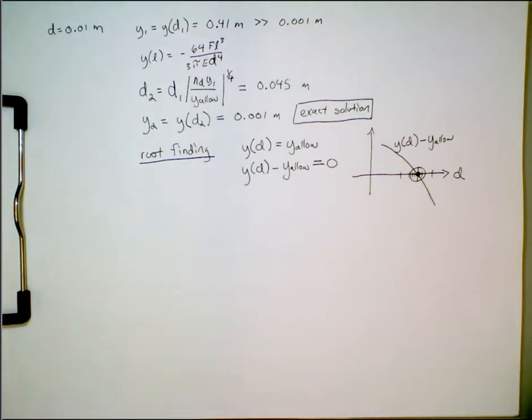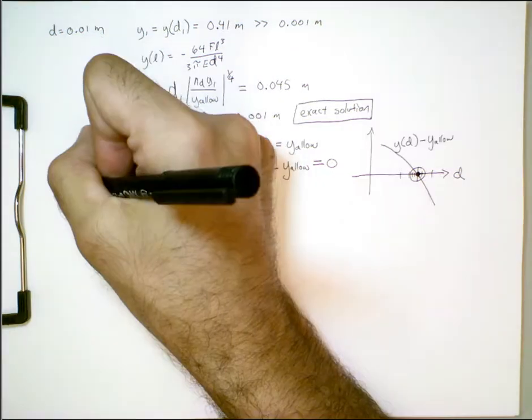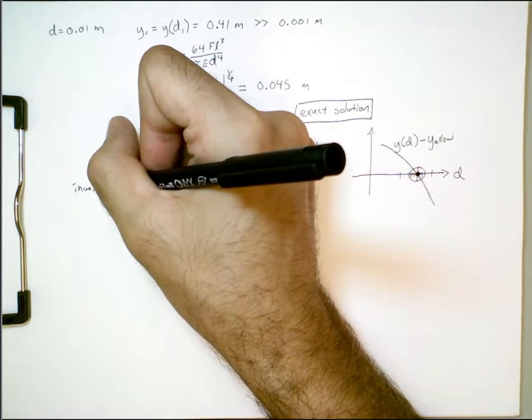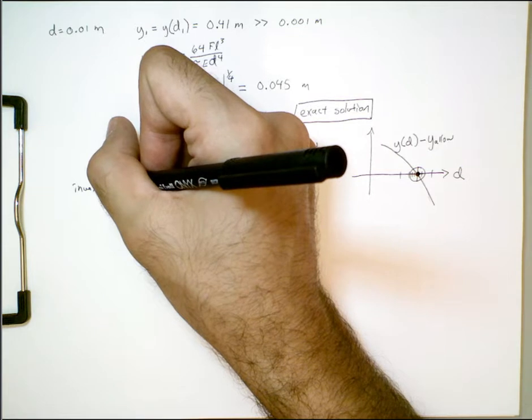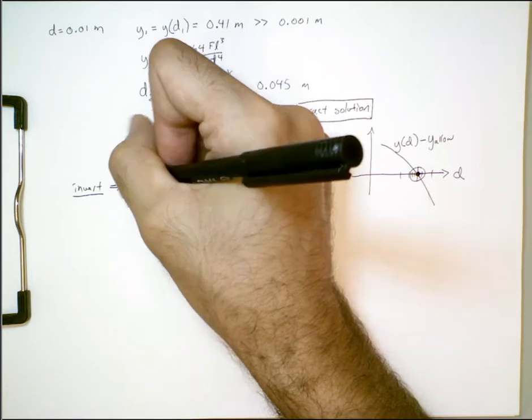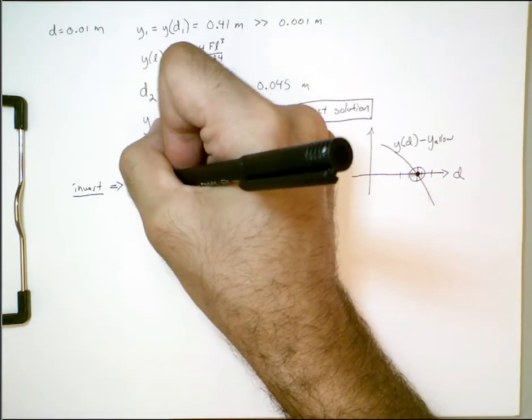In thinking about how design is the inverse of analysis, this is a good example of that. In simple cases for shaft design, we can invert the analysis formulas and solve for the design variables. So in this case, d, the diameter, would be the design variable. And if you remember, earlier in class we looked at a graphic that described this idea of how design is the inverse of analysis. So if we invert an analysis formula, sometimes we can come up with a design formula.